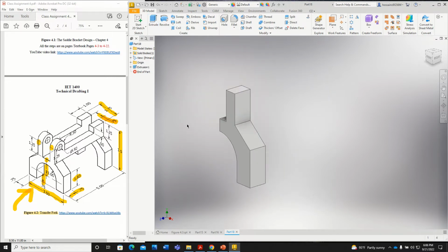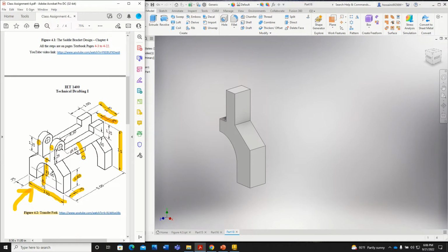After that, I need to assign a new plane which will be used as a mirror plane. This new plane should be in the middle of the whole thing. It should be here. So I'm going to use that mirror offset, which is half of 5, that is 2.5. You can find the assigning plane commands here.